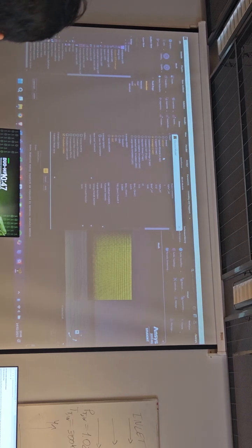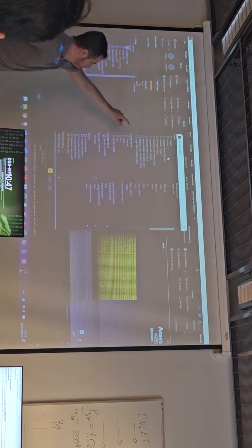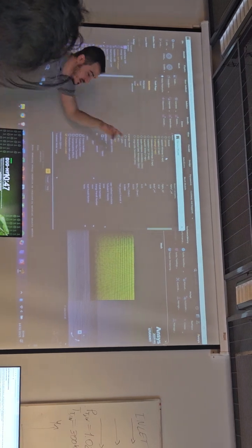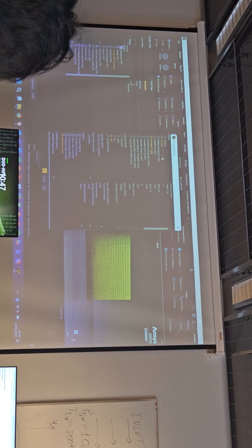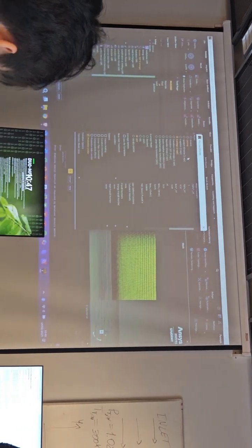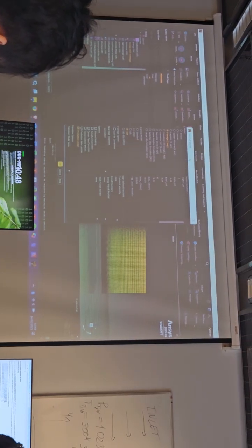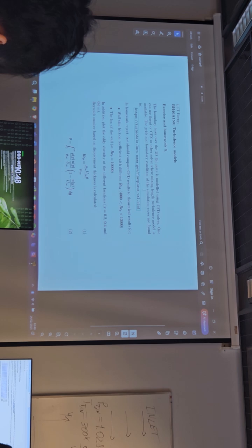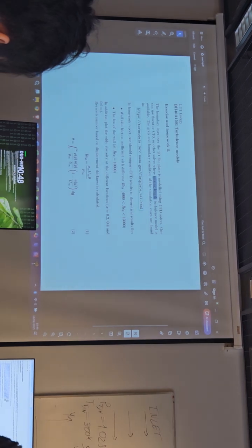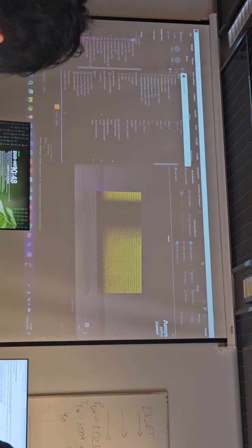Then we have laminar and the other turbulence models. We use Spalart-Allmaras from next. Then there are two equation models, so other models that we will study and use later. But now we need to solve it as said in the exercise using the mixing length turbulence model. We don't have it here, so we need to enable it.